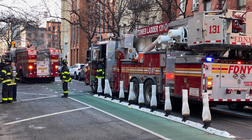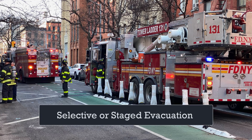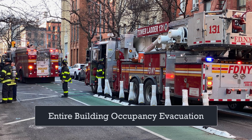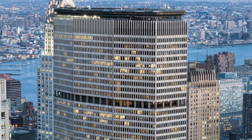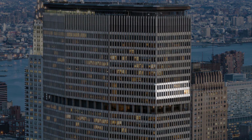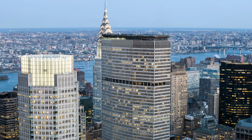A building's specific evacuation procedures typically follow one of two evacuation protocols as promulgated by the AHJ: selective or staged evacuation, or entire building occupancy evacuation. Very tall high-rise buildings might also incorporate emergency refuge practice, where occupants relocate several floors below the incident floor for safe haven. Selective evacuation is generally conducted in larger high-rise properties and is regarded as the most effective method in protecting the life safety of high-rise building occupants.